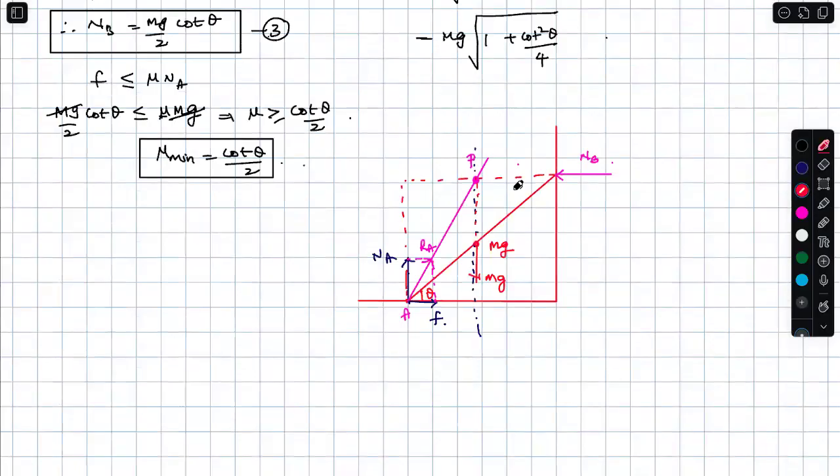The only three forces are actually acting on the rod. Bhavana, what are they? One is a weight force, the other is normal reaction force, the other is a resultant reaction force. Now, what are the situations that you are facing? These three forces, if you extrapolate the lines, are intercepting at a point P, such that about P, the net torque of the system is 0. If such a situation exists, it's in rotational equilibrium. So always you need to find such a point about P,